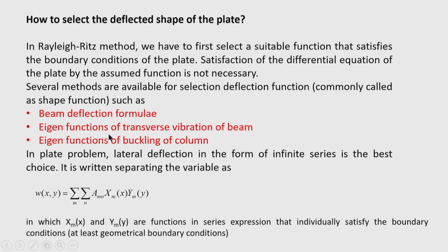Transverse vibration of a beam is generally represented by a fourth order partial differential equation. Now, when you want to find the eigenfunctions of the beam vibrations, we again use the separation of variables technique and arrive at an ordinary differential equation of fourth order in terms of one variable.